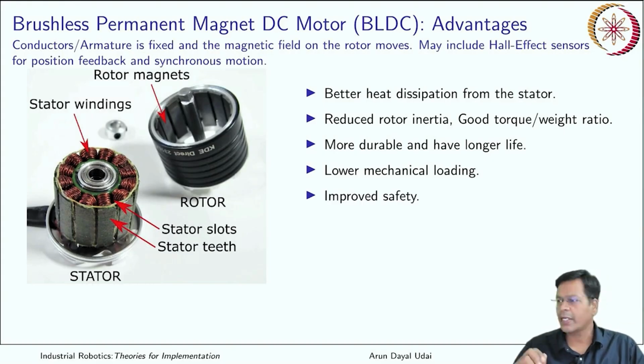Okay, and then this type of motor is very, very safe, because there are no brushes. There is no fire hazard as such. This type of motor can get into atmospheres like inflammable atmospheres, like mines or those types of locations where you can have potential areas with plenty of methane and inflammable gases all around. So they don't have any sparks within the motor, and the gases cannot enter a zone which has sparks which can cause fire. So they are very, very safe as such.